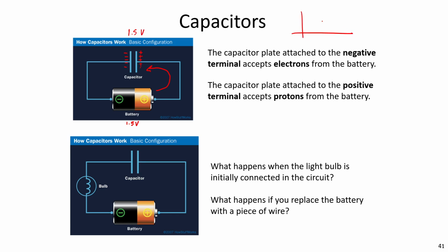The voltage of the capacitor, VC, will be charged until full, 1.5 volts, right? And what about the current? The current will flow until the voltage is full, then the current is 0. No current anymore, right?